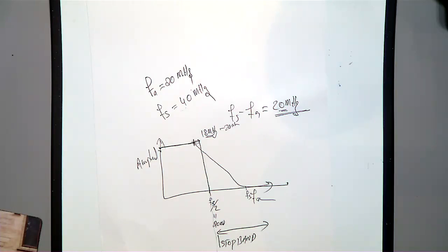Then you can say, yeah, that is a tight situation, the lecturer put it so that we would understand the effect of the sampling frequency. For example, in our case, the bandwidth is equal to 20 megahertz and the sampling frequency is equal to 40, and then we are in a tight situation. But if you increase your fs to 80, then we can get 80 minus 20, and we get some more room. In order to understand that, our lecturer made that one tight.